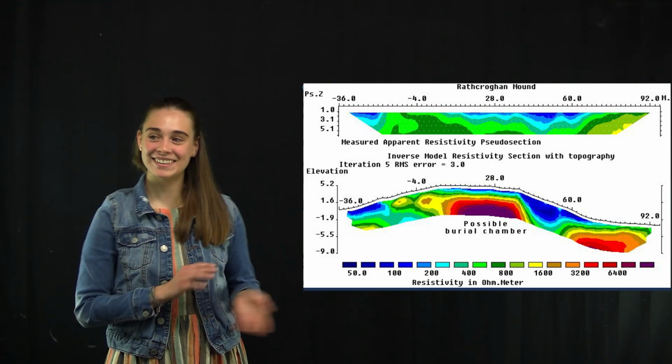And on to seismic. All right, let's talk about seismic. Seismic is basically sending sound waves into the ground and listening for what comes back. The way we do this is with dynamite, or what we're going to use is an accelerated weight drop, which is just a big heavy hammer. These waves are defined by velocity, frequency, and wavelength, and in seismic we want to know all three of these parameters.